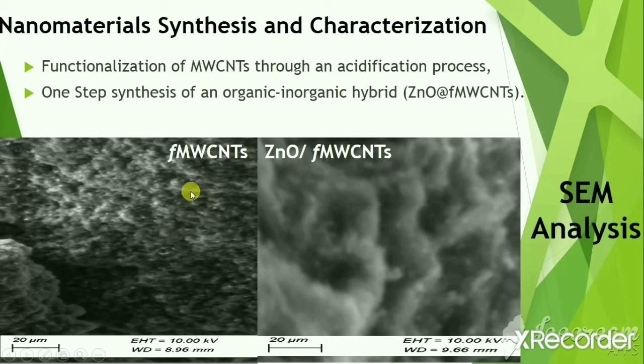But if you compare it after the incorporation of zinc oxide nanoparticles on its surface, you can see that there is a deformation on its surface, and it had a shrinking phenomenon here, and walls were created on its surface like a honeycomb structure. Also, we can notice clearly some white points indicating the presence of metal, which is zinc oxide, on its surface.